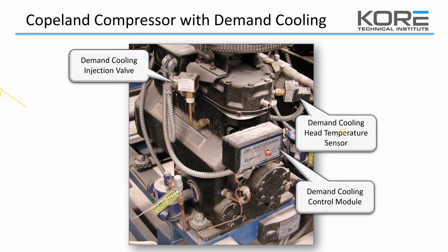But really, unless you have something that can slow the compressor down like a VFD, liquid injection is really the only thing you can do for high temperature scenarios and the compression ratio scenarios that you run into. So there's a few things that are industry standard that are done to help curb the high temperatures that we see, especially in the low temp applications.